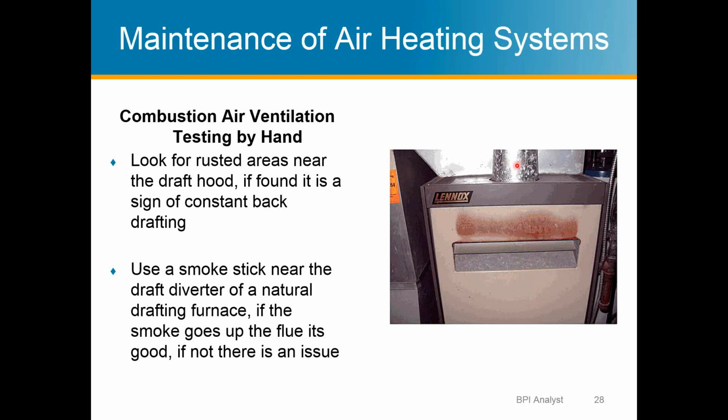Well, when the exhaust is cold at startup, sometimes exhaust gases can spill out. That's okay if it does it for less than 60 seconds. But this is a sign that it's been happening. It's been happening for a while, and it may still pass. It may only spill at the very beginning of startup, but that's what this is a sign of.